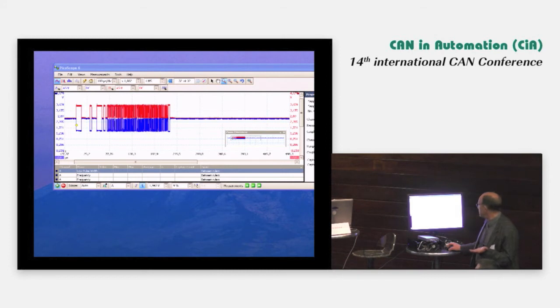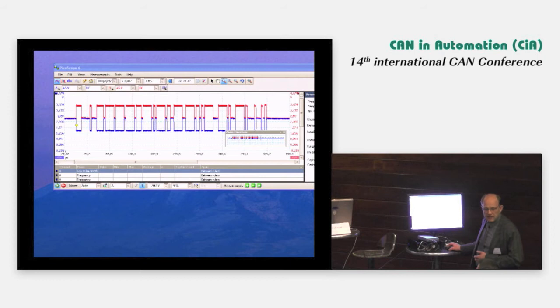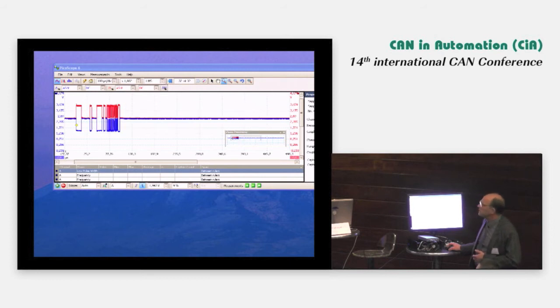In this case, we can select a number of bytes. If you have 8 bytes of data, you see here the CAN-FD frame is very short compared to the standard CAN with 8 bytes of data. So even with 8 bytes of data, it is very important to switch to CAN-FD, because you shrink it a lot, since you also shrink the CRC.